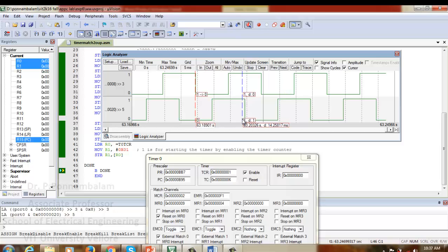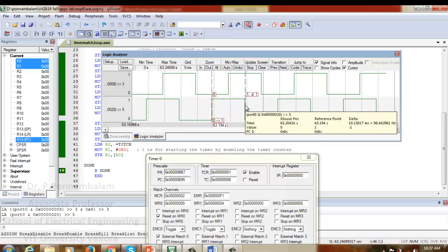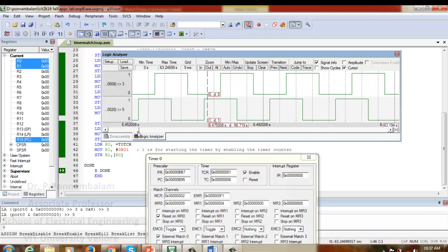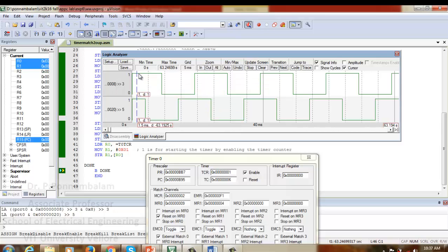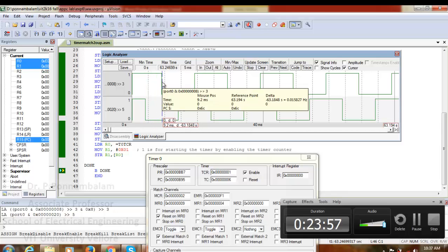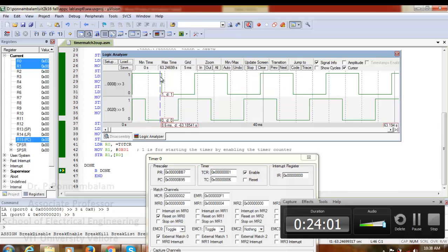In case you want to see P0.5, you can see it is also 10 millisecond, but we have specified 4 inside T0 MR1, meaning 5 millisecond, yet we are getting 10 millisecond. This is because, as I have already mentioned, if you see the initial part of P0.5, we will understand. Both have started, and you can see at 5 millisecond this is getting toggled. When it is toggling, you can see that this is going to 0, and after 5 millisecond when P0.3 is toggling, before it is getting toggled, it is getting reset.